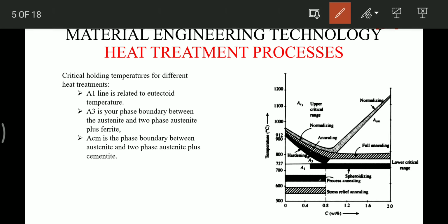As we know, heat treatment is heating to a particular temperature, which we get from the phase diagram, and the cooling rate determines the final microstructure that will be formed. Phase diagrams only cover composition and temperature, and do not have anything to do with time. For that, we use TTT curves or CCT curves.